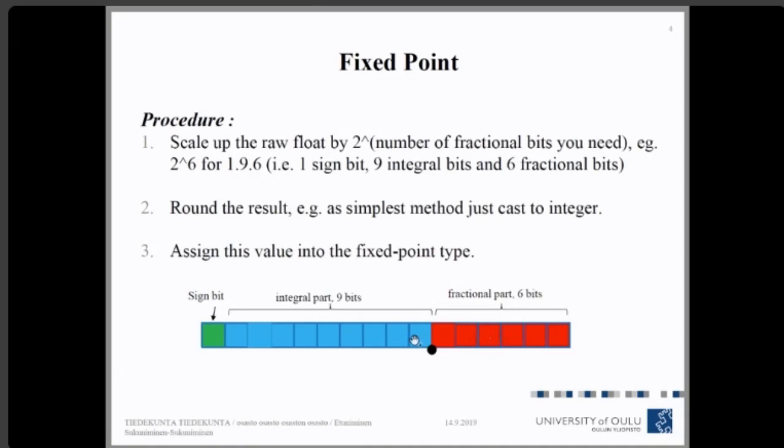If the fractional part is larger, that means we will have high precision, and so to speak, less risk of underflow or rounding. But on the other hand, because we now have a smaller number of bits dedicated to the integral part, we will have a smaller dynamic range.